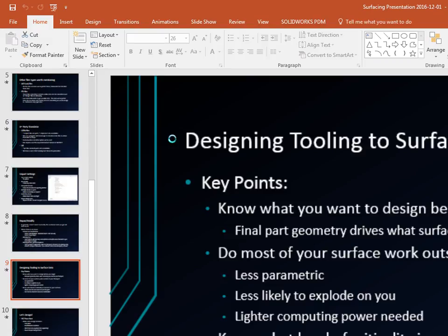And I don't want to just extrude a boss up to this one, extrude a boss up to this one, extrude a boss up to that one. I just want to have one boss that extrudes up to, basically what would be this face if it was continuous. So that means I need to make a continuous face on here. So I'm going to take these surfaces and I'm going to rip them out of the part. I'm going to do a save as. And again, I'm selecting multiple faces that are touching each other, so I'm going to take IGES so that they heal together instead of this being an individual body and this being an individual body and that.